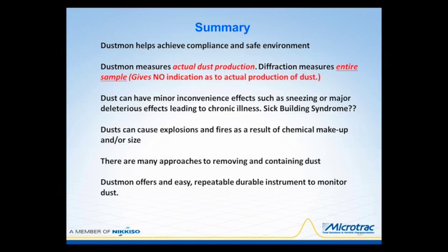So in summary, the Dustmon helps achieve compliance and a safe environment. Dustmon measures the actual dust production. It doesn't measure the entire particle size distribution. Diffraction measures the entire sample and provides the entire particle size distribution, but it does not give any indication as to the actual production of the dust.